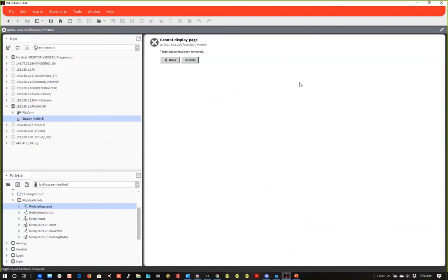All right, that's a good point. And then also, there's a dedicated CPU for the switch. One of the things you hear people talk about is a broadcast storm, where all of a sudden there's so much traffic on there, it ends up taking down the switch. Well, if you don't have a dedicated CPU for it, your controller is going to suffer as well, your logic and all. But since this has a dedicated CPU, you don't have that issue.